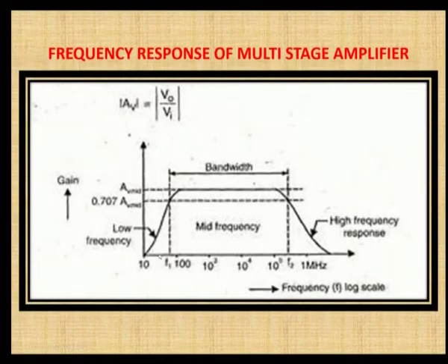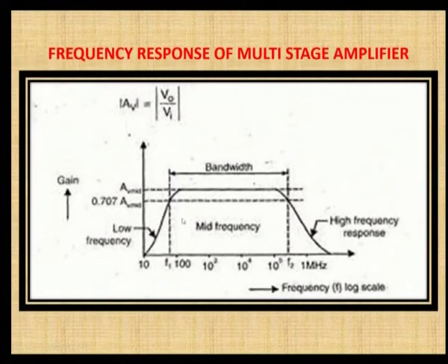So, in x axis it is the range of frequency and in y axis it is the gain of the circuit. When you look at the graph, for the lower range of input signals frequency, the gain is slowly increased, and this is the mid-band frequency. In mid-band frequency the gain is always constant as A, and at higher frequency the gain is reduced slowly, and this roll off is because of the capacitance effect and the active devices in the circuit. These are the reasons for this roll off rate.